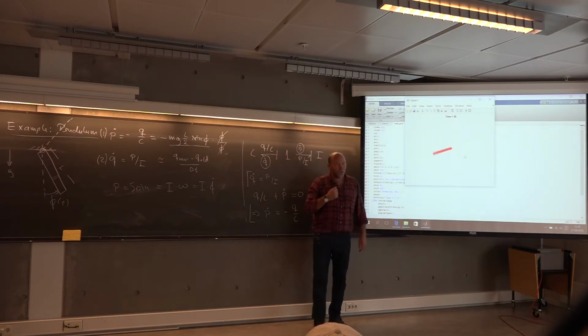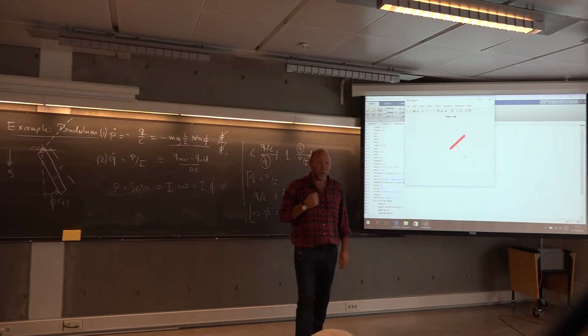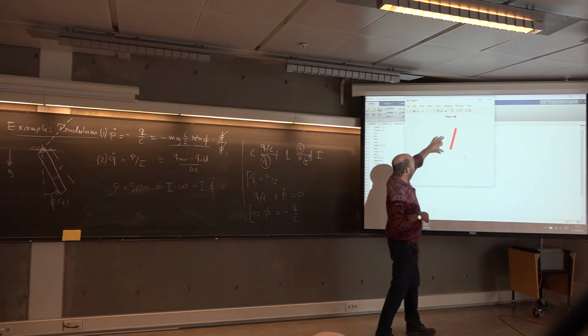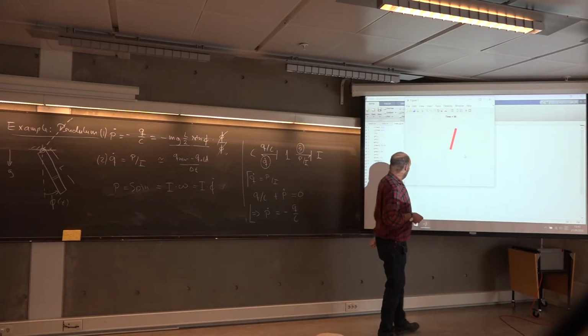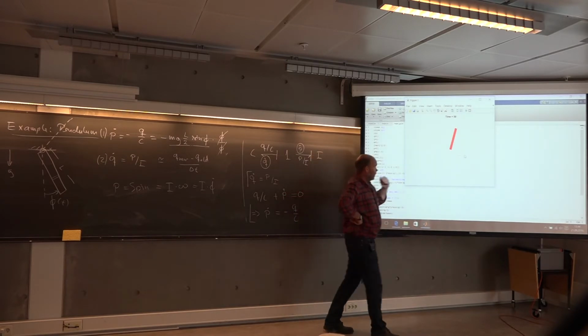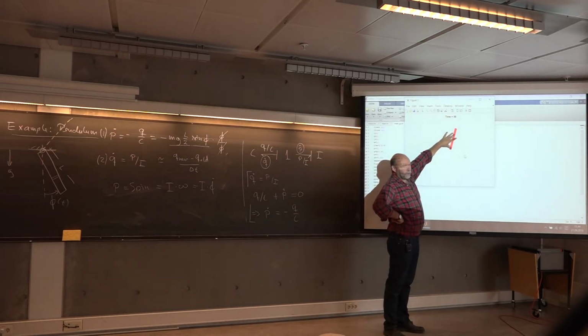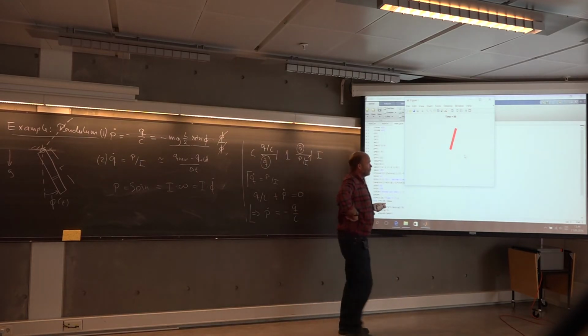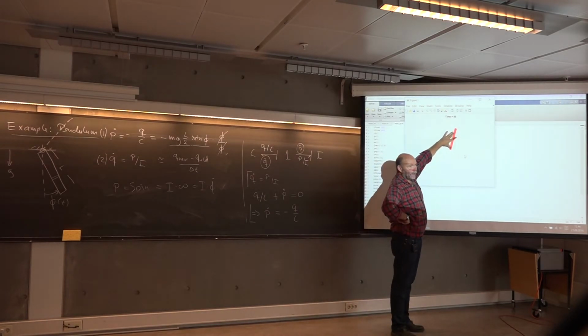It's a very nice way to create animations in MATLAB. You just modify the figure. You're changing the position of this rod in the time loop. Another possibility to create animation in MATLAB is to remove this window and then print it as a new window every time, but that will not go so fast. It's also another option: remove it by printing it again with white color and then print the rod again in the new position.